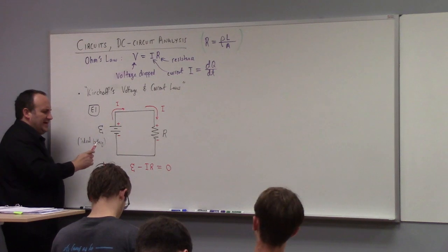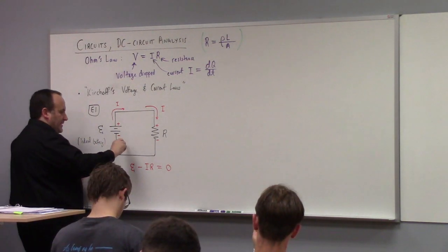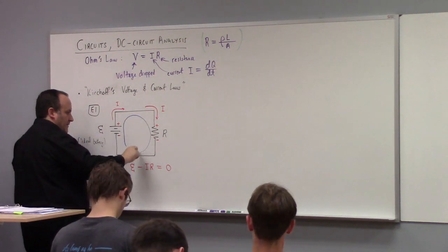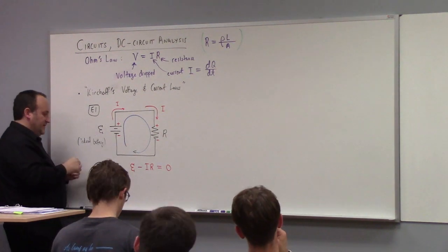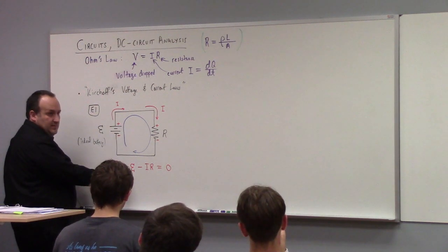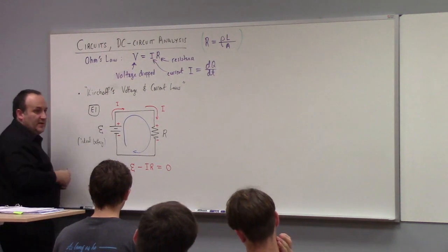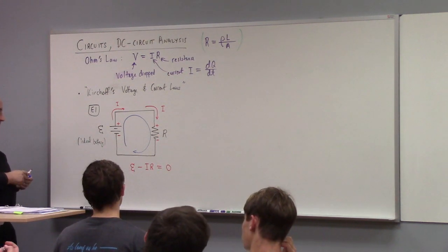So the way this is working, guys, is we're going in a loop like this. All right, and you notice the difference. Minus to plus, I add. Plus to minus, I subtract. All right, so that's Kirchhoff's voltage law.